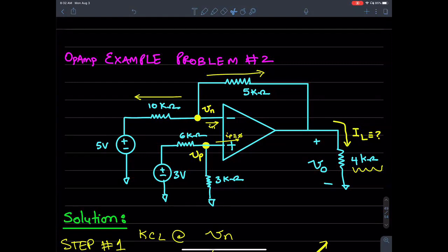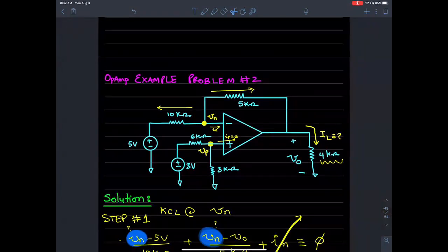So if for some reason you find yourself not able to solve it, I would say that inhibition is in your head. There's only two steps that you have to do. Apply the KCL and apply the two rules. That's all there is to it. Be strategic, take a step back, look at the big picture, and then strategize on how you want to unravel the problem. Questions, please.